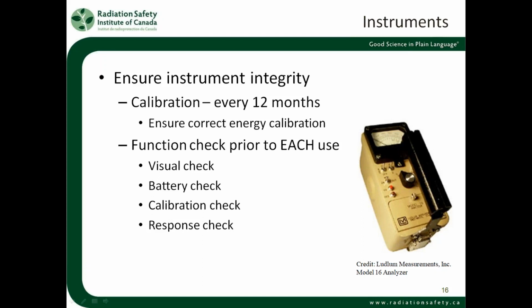When we're using our instrument, we should have a verification that it's in calibration. So we're going to pick it up, look at the calibration sticker, and make sure that it's in calibration. And we should do some sort of response check. So we're going to put our instrument near a radiation source, our X-ray machine or a check source that we've purchased, to make sure that the instrument actually responds. Because if we don't verify that it responds, then when we go do our survey, we may think we're getting a 0 result when in fact the instrument simply isn't functioning. So we need to make sure that instrument is functioning before we actually use it.